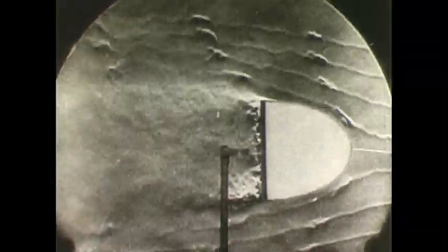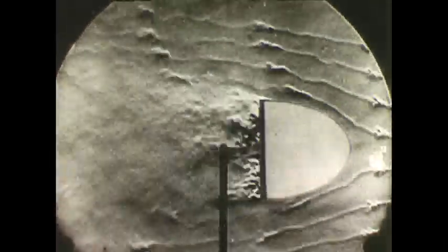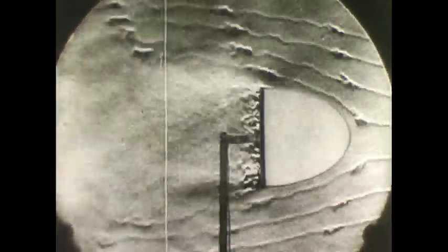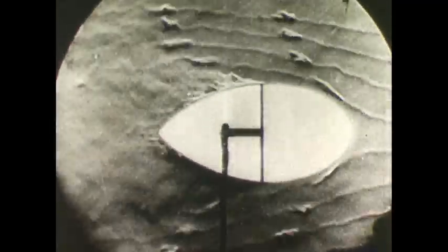Turbulence is affected not only by the attitude of an object, but also by its shape. The turbulence due to this plate is decreased by putting a nose on the plate without decreasing its width. By adding a short tail, we decrease the turbulence only slightly. A longer tail shrinks the wake to very small dimensions. The drag of the streamlined plate is only a small fraction of what it was.